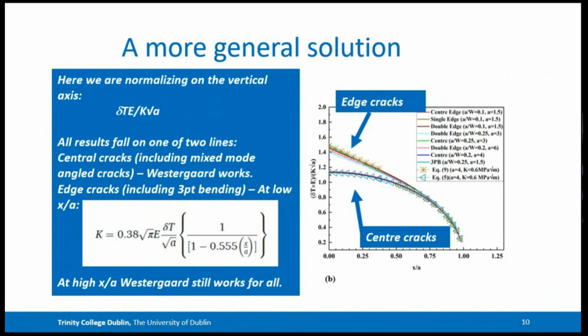And then we went on and we tested quite a range of other loading, other types of specimens, including central cracks at an angle. So then you get shear loading as well as tensile loading, and so the cracked faces slide as well as opening. And we also looked at 3-point bending. And in all cases, we found that the results fell on one of those two lines, all the center cracks on this line, all the edge cracks on this.